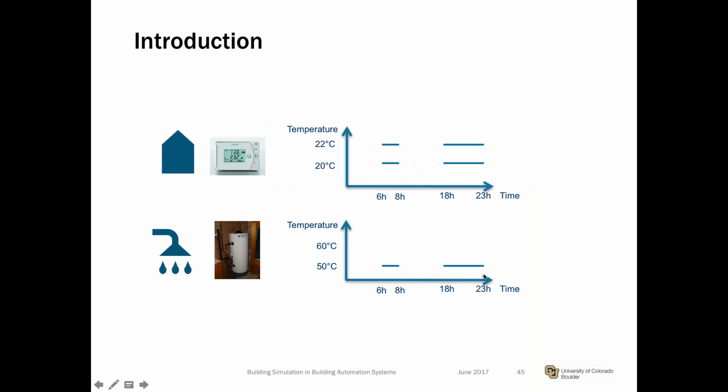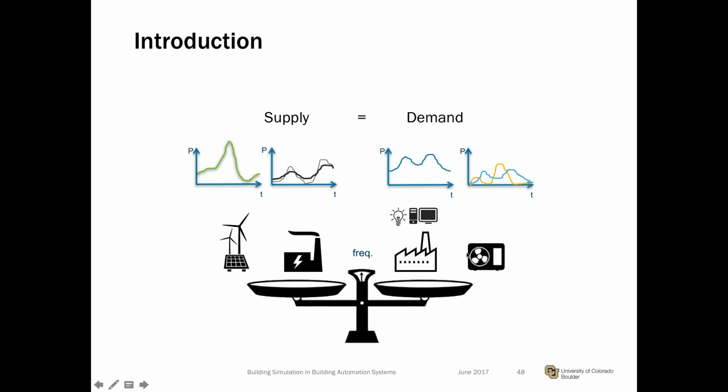Let's take a heat pump system. Historically, the temperature set points chosen for the homes and for the domestic hot water system would be such that they are basically hovering, for the heating case, around the lower set points. You can see how the domestic hot water system is cycling to stay there. But what if we were intelligently changing set points and overcharged the building and the domestic hot water system during certain times of the day and then let it float for the rest of the day? And in this integrated assessment, we're now modifying the demand.